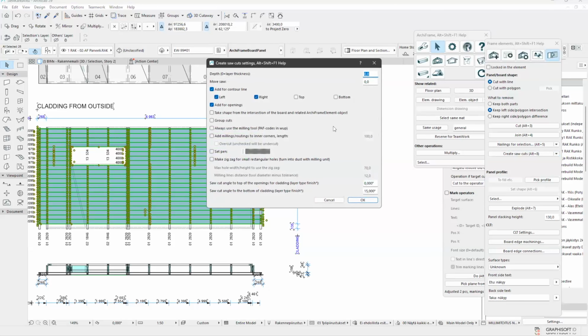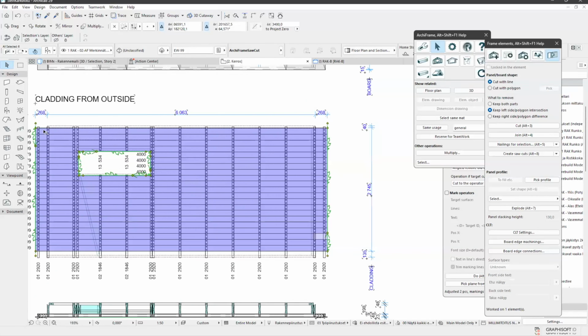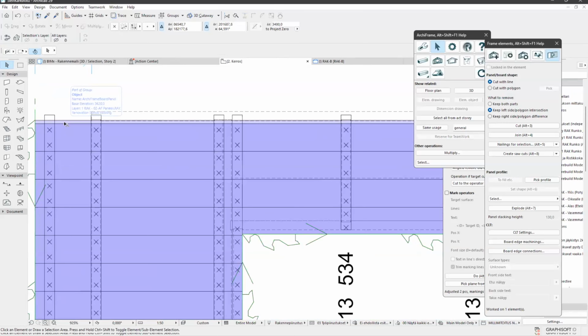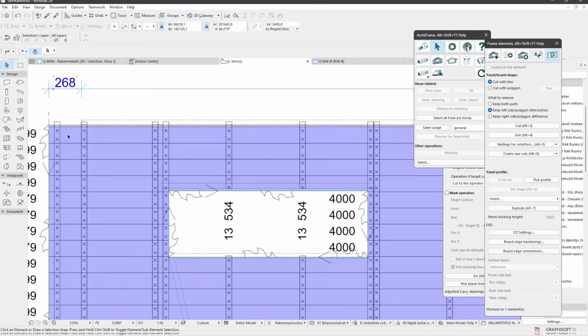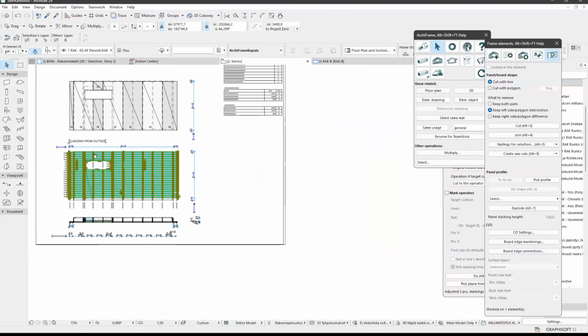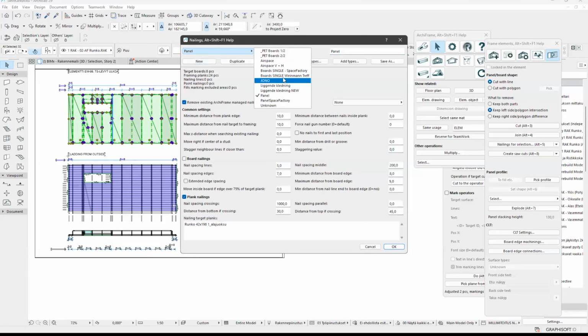Let's add the saw cuts, not to the top and bottom, because we have horizontal cladding, and usually we try to finish this into a full cladding piece, and it looks like that is the case here. Then the same to the windshield boards. So I take the windshield boards and the framing behind it and add nailings.